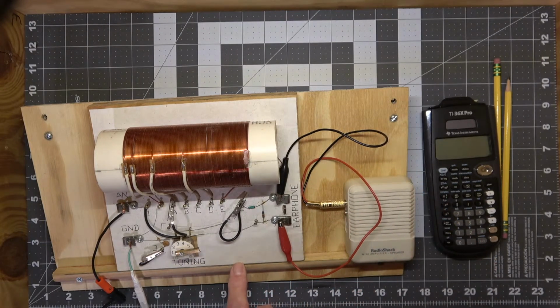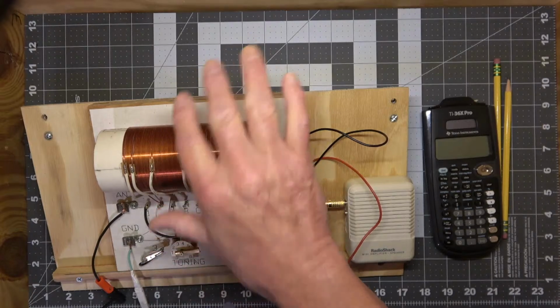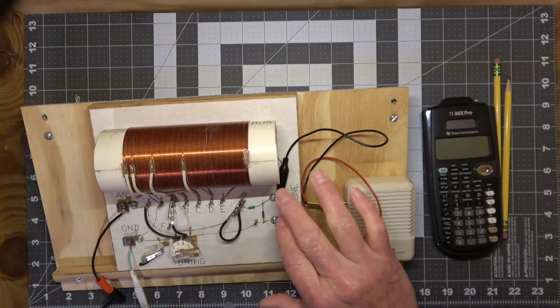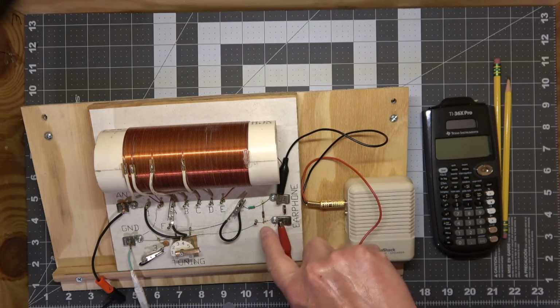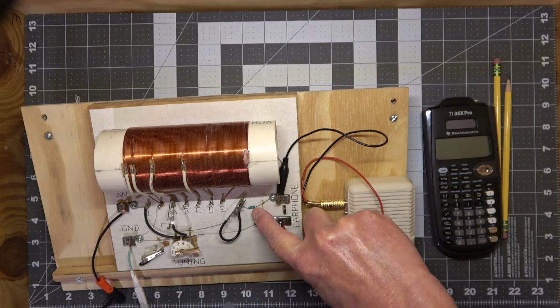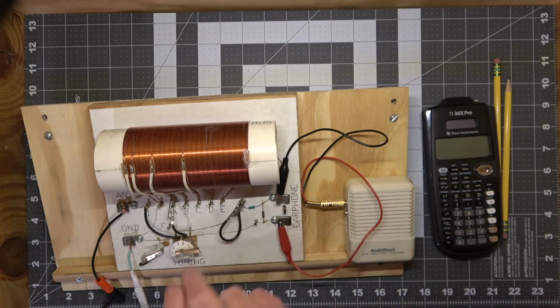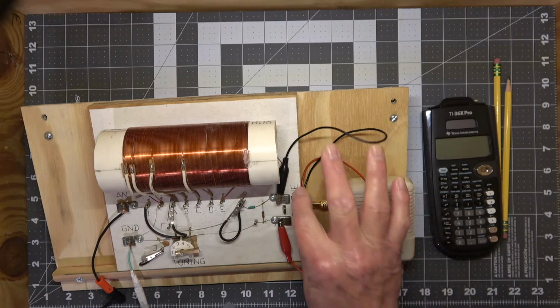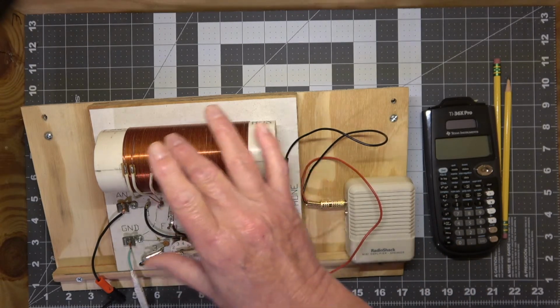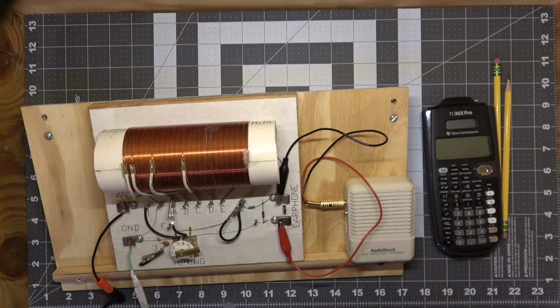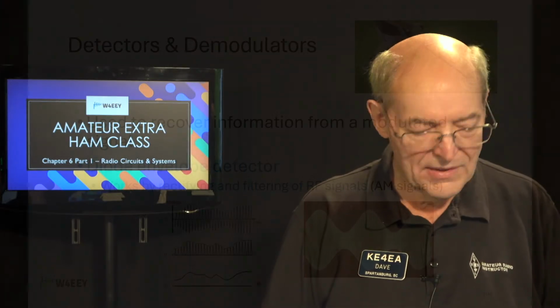It didn't work before class either, but at home I do have a strong AM station, and I was able to hear it. The way this works is the diode, which is the detector, rectifies the incoming AM signal, and you can actually hear it. When I found this at a Hamfest, I had some friends there, and I told them I don't need my fancy transceiver anymore because I've got this wonderful new crystal receiver, but nobody believed me, which is a good thing.